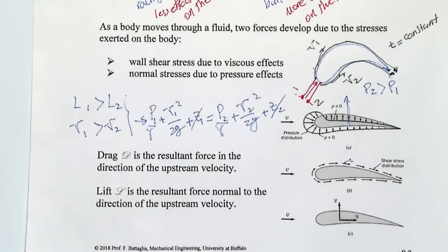So you can apply this equation and calculate the lift based on the flow that is outside of the boundary layer around the object. That's the way you can calculate the pressure. So there is a meaning behind why you have normal pressure and wall shear stress at the same time, and you will have lift and drag over the body.